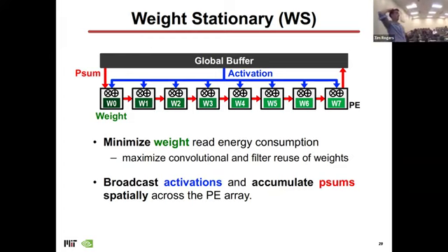So you can envision this as maybe there's a buffer that goes to the interconnect, or it's a direct connection. If it's super aggressively timed, I guess you could have one cycle, right? You put the bits on the output of the MAC, and then on the next cycle you wire the outputs of that directly into the input of the next MAC.